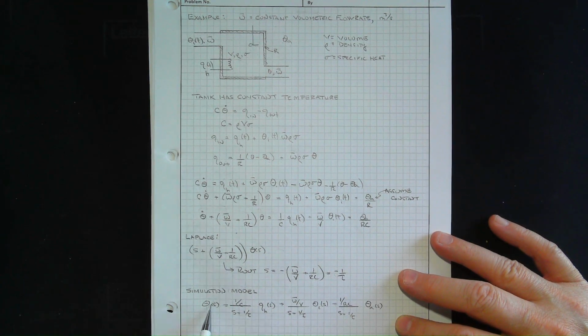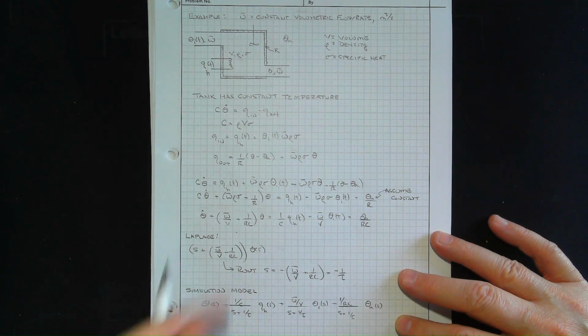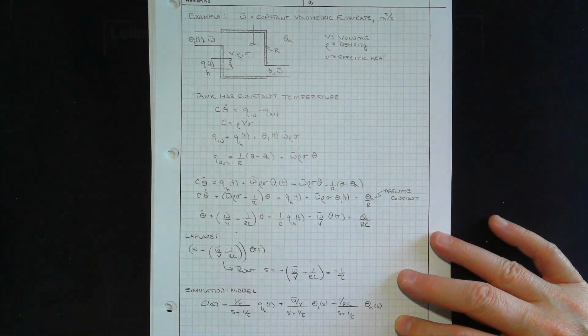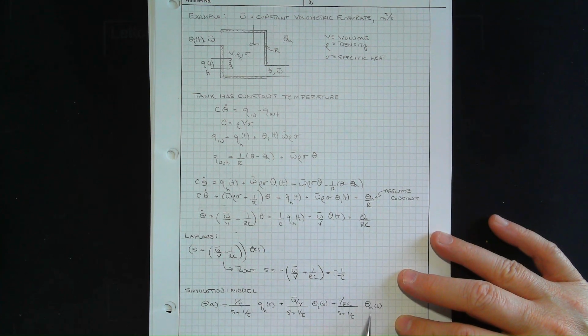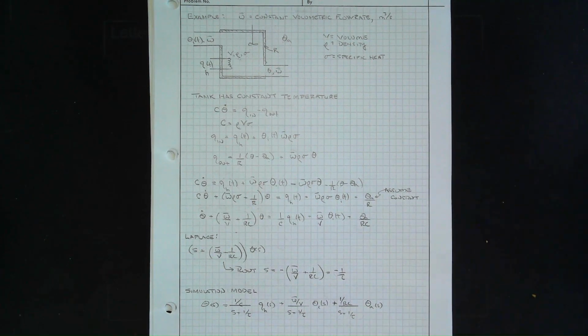This is affecting the heat in this vat. Then you have the heat that is supplied by the flow, and it adjusts the heat in the vat according to this transfer function. And then you have the heat that's outside, and that adjusts the heat according to this transfer function. And there we have, oops, no, that's a plus. And that's all of them.